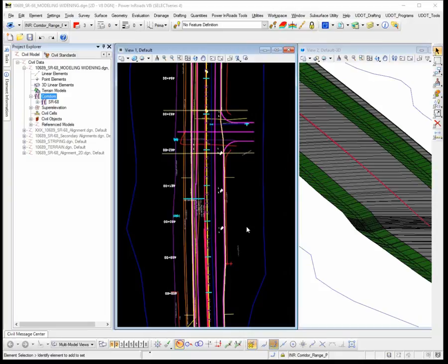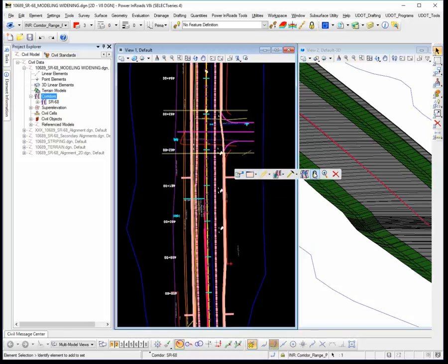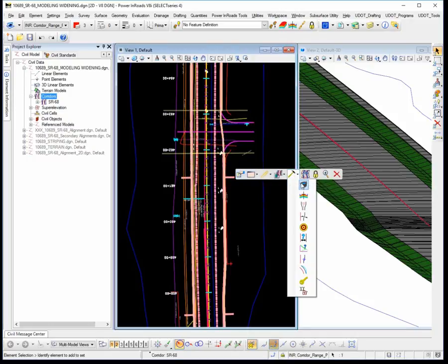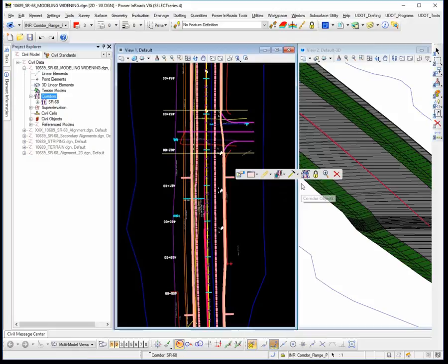Another important aspect to reducing the time of processing when you're doing work within corridor designing is to take advantage of corridor activation of the rules. So if I select a corridor here, for example, you see this padlock, I can select that it's locked right now, but I can select it to deactivate it or let it think that it's not a corridor. I can get to that same tool over in my corridor objects dialog.